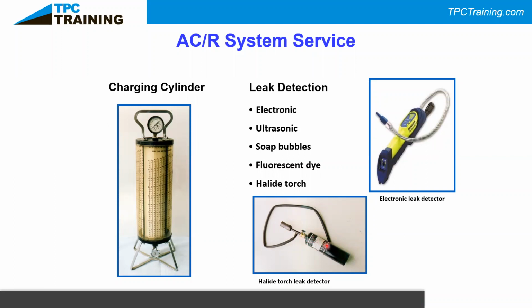The idea being you screw in a propane torch and you turn it on and have a flame right up in here where I have this red dot. And when that flame comes on, you take the hose and you sniff around your line. And when you find a leak, the refrigerant coming and reacting with the flame would cause it to turn a bright purple color. And that's when you know that leak is at that spot.